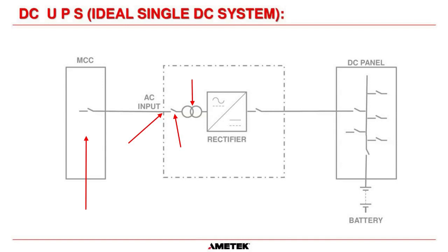Now, in most industrial charger situations, we're going to be charging at a 120 volt nominal. So you're usually going to connect your charger rectifier to a 60 cell lead acid battery system. Now, obviously, there are other voltages. You can do 48 volts, 24 volts, and sometimes higher. You can do 240 volts. But in most applications, it's going to be 135 volts. Well, sorry, 120 volts nominal DC. So what the transformer does is it steps the 480 volts down to a suitable AC voltage that can then be rectified to the correct DC output that we require.